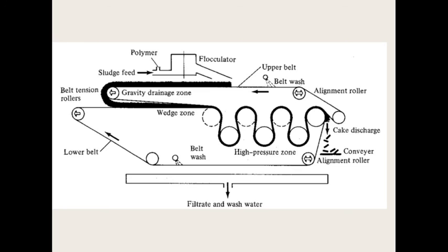So this is all about the sludge treatment methods: anaerobic digestion, thickening and stabilization of sludge, then dewatering methods, then hygienization of sludge, sludge drying beds, then composting of sludge. We can do the composting with green waste. The sludge can be composted with green waste, which also produces compost that we use as a fertilizer. Incineration we can do, we can burn that sludge.